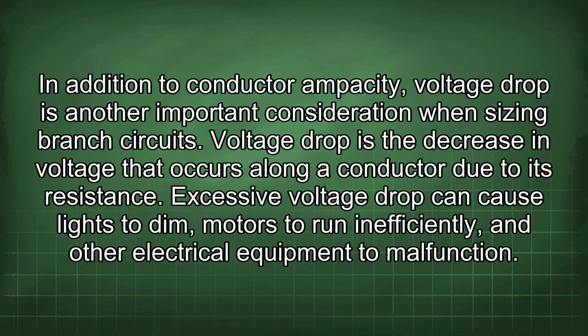In addition to conductor ampacity, voltage drop is another important consideration when sizing branch circuits. Voltage drop is the decrease in voltage that occurs along a conductor due to its resistance. Excessive voltage drop can cause lights to dim, motors to run inefficiently, and other electrical equipment to malfunction.